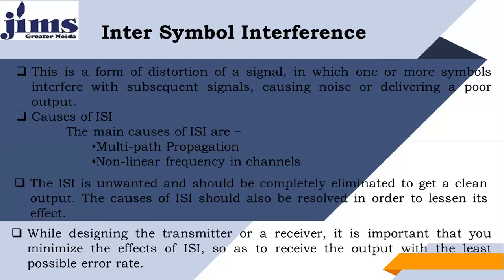When this type of signal reaches the receiver, and the inter-symbol interference is very high, the receiver is confused in detecting 1 and 0 in the right way, and that creates noise also. So the chance of error is that when 1 was sent by the transmitter the receiver declares 0, and when 0 was sent the receiver declares 1. This is the case of error that comes in the picture as far as digital communication is concerned.